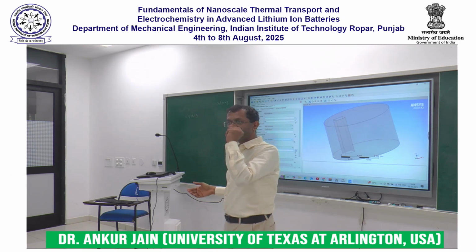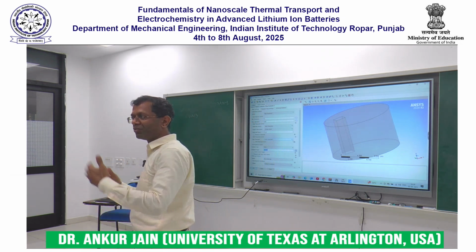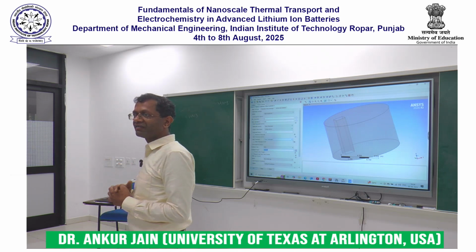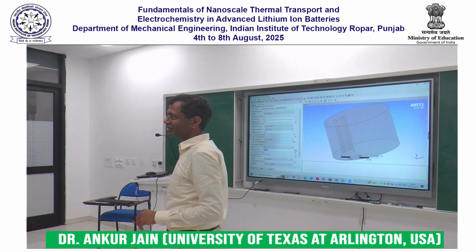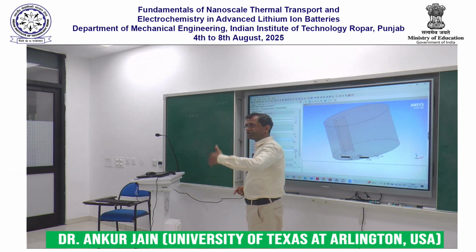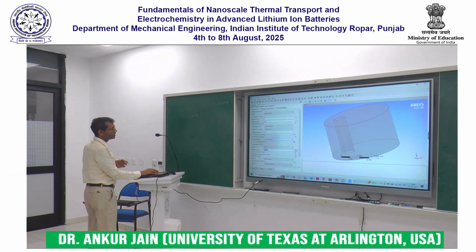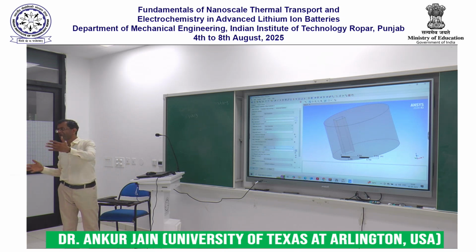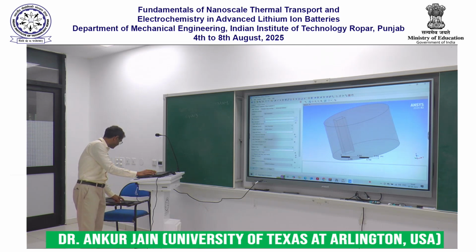As an early user, it is okay for you to just leave the default values, but as you become more and more of a sophisticated advanced user, you've got to understand and learn what each of these things mean and do. Roughly speaking, the lower the residual, the higher is the computational cost, but also higher is the accuracy. I have learned through the years that this number that ANSYS gives you by default is actually too large. I need my residual to be much smaller, and I need the number of iterations to also be at least 200.